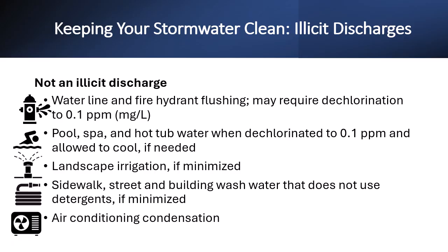Landscape irrigation if minimized. This means using good watering practices because overwatering or having irrigation misdirected onto hard surfaces could lead to an illicit discharge. Sidewalk, street, and building wash water that does not use detergents. If detergents are used, the soapy water cannot enter the storm drain or it is an illicit discharge. Any air conditioning condensation is not considered an illicit discharge.